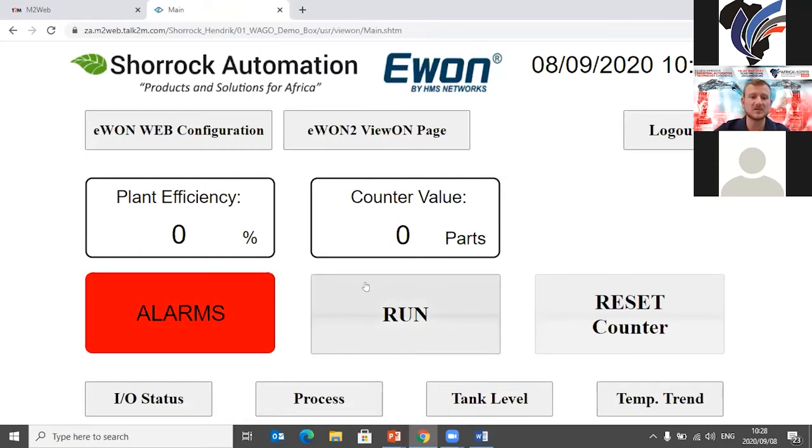I could also remotely stop and start an application. So if I click here on run, it would in fact start a counter within the PLC. It could, for instance, be to start the process, remotely stop and start the pump, for instance. So those are actually one of our use cases or applications that we come across quite a bit: customers that want to do remote stopping and starting of pumps and view some status monitoring, maybe view the power consumption of their pump station. Okay.